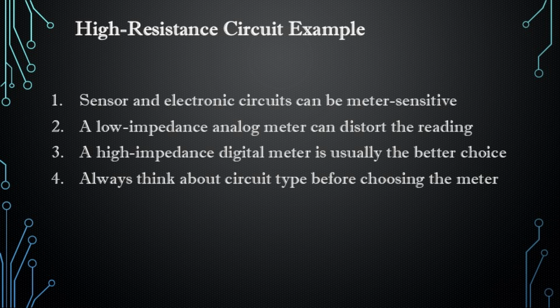So one of the more mature habits a technician can develop is this. Before testing, think about the type of circuit, ask what the circuit does, what kind of resistance it likely has, and what kind of meter behavior is appropriate. That kind of thinking separates casual testing from real diagnosis, and that is what we're after.